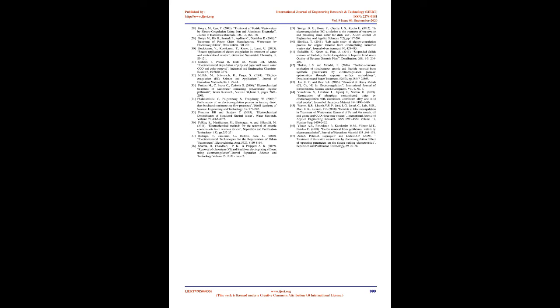Effect of applied voltage. In all electrochemical processes, applied voltage is the most significant parameter for controlling the reaction rate within the electrochemical reactor. Mala et al. 2001. It is well known that this variable determines the production rate of coagulant, also adjusts bubble production, and hence affects the growth of formed flocs.